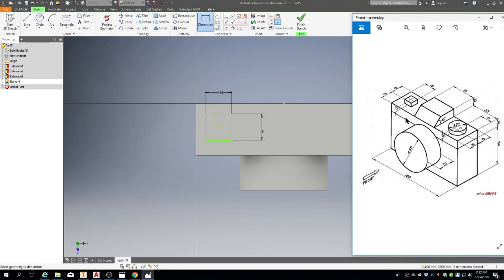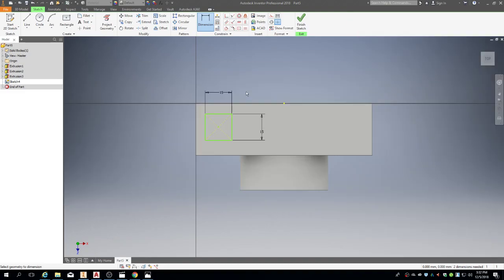I don't actually think that is a 15 by 15. I think it's a 10 by 10, and we're just missing some dimensions here. Oh, well, that's easy to correct. Alt-Tab takes us back to our drawing. Click on the dimensions, change it to 10. Click on the dimension, change it to 10. That's better. Now, we're going to dimension from the very center of this to the edge, and come up and make that 15. That's what they were talking about. We also want it centered on here. It's 30 wide. Quick math tells us that from the center to this line should be 15.